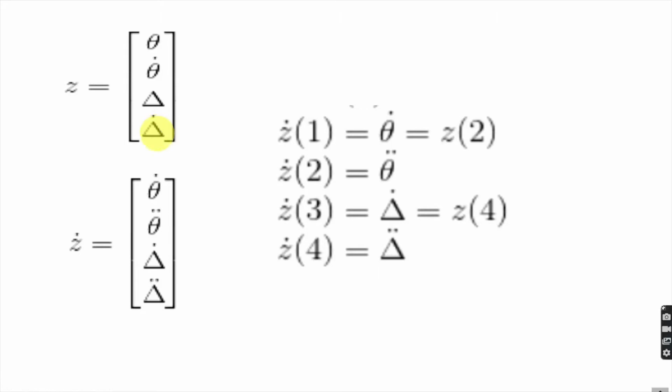So now we can solve our equations and reduce them and use ODE45 with this simple trick, because we are solving now for z dot, which is the first derivative of z. And basically we're going to be using some matrix math where z dot is solved for using ODE45.